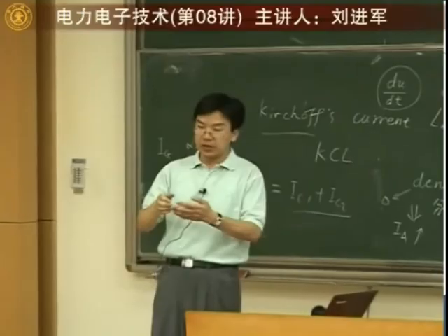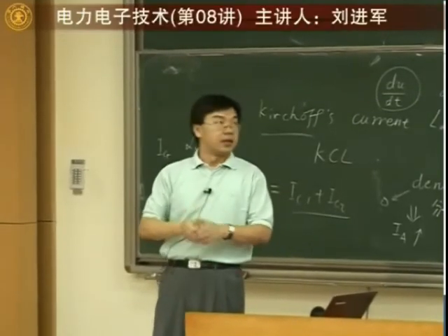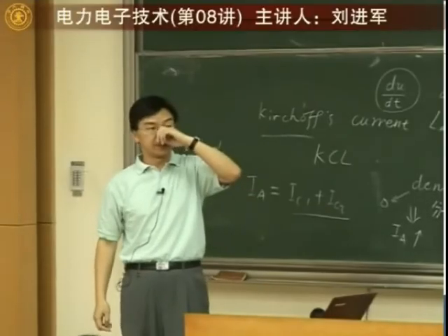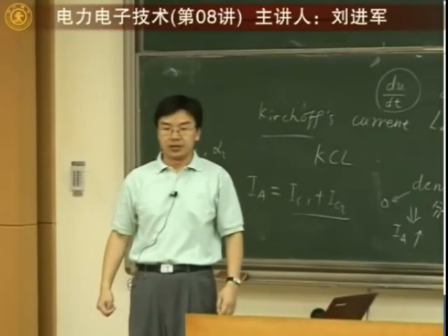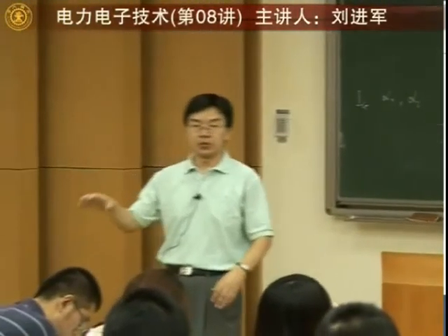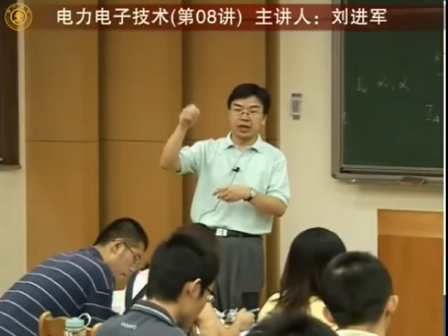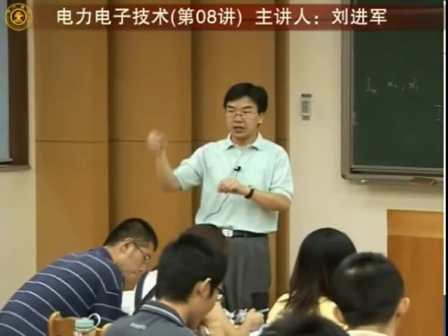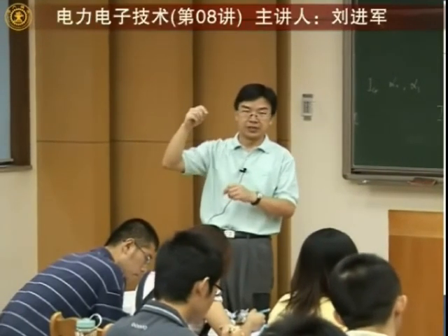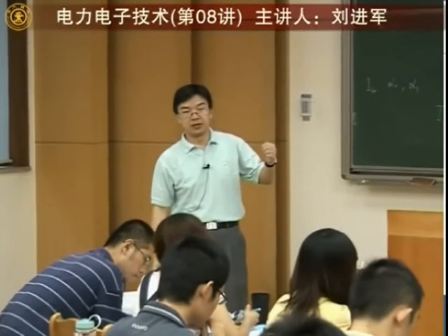That means this voltage is increasing too fast. Then that will also cause the turn on of the thyristor. Even if you do not inject gate current, you just apply a positive voltage to A and negative voltage to K, and that voltage is increasing very fast, that will also turn it on. That's not good. We do not want that to happen.